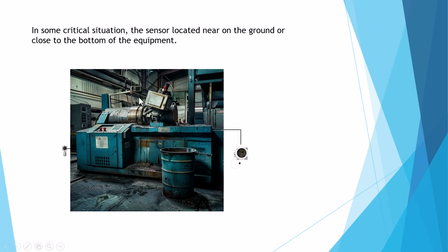So how to do this? He uses the K factor 2.2. For example, 2% LEL is captured, then times 2.2, it goes to 4.4%, which is more than 4%. So the 4 to 20 mA signal goes to the transmitter. The transmitter activates the alarm at 4.5% LEL. So that's why we use the K factor to activate the alarm on the transmitter. Okay.